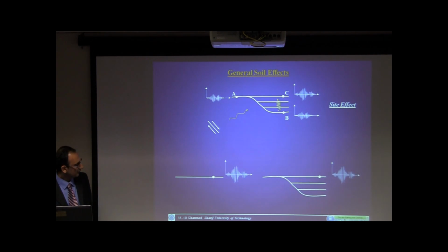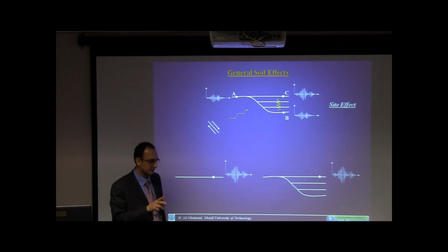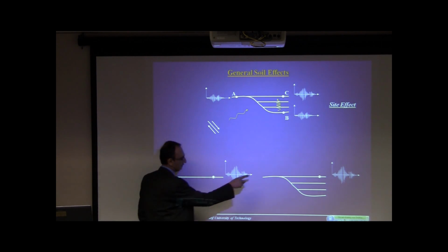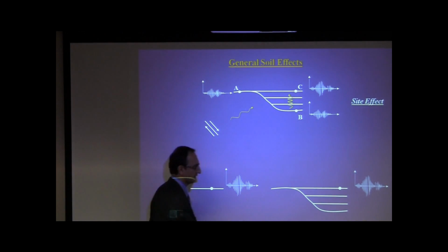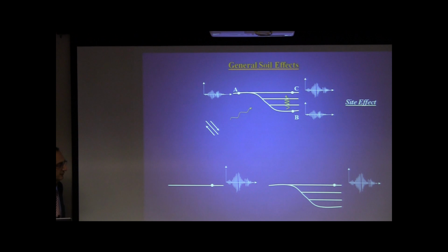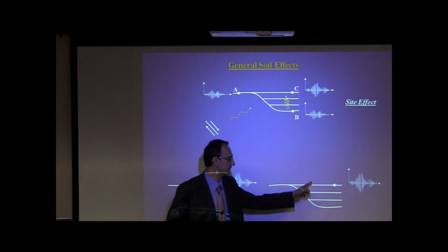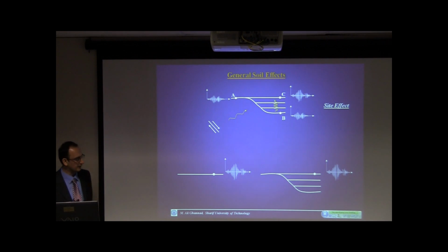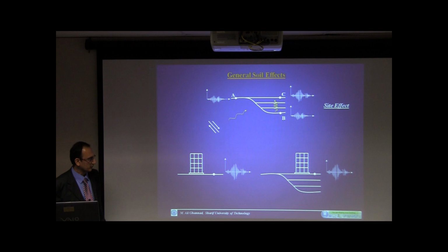Now, consider that we have two different sites, but by chance, we have the same ground motions. This is on the rock, and this is the soil. But by chance, just suppose this is after the site effect, and this is the original record on this rock. We have the same records, but the response of identical structures on these points would be different again.